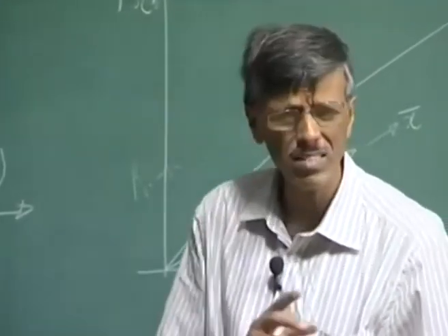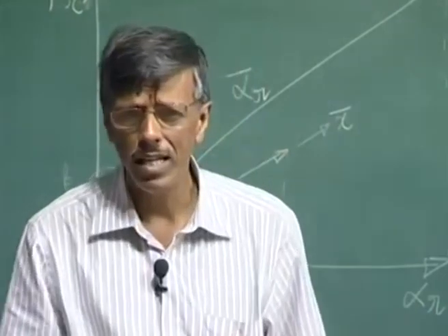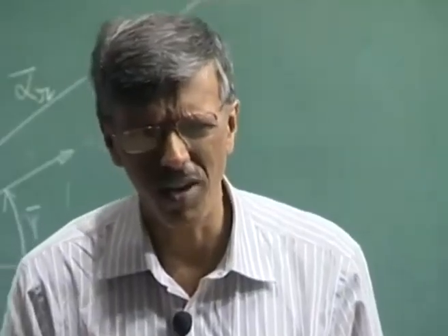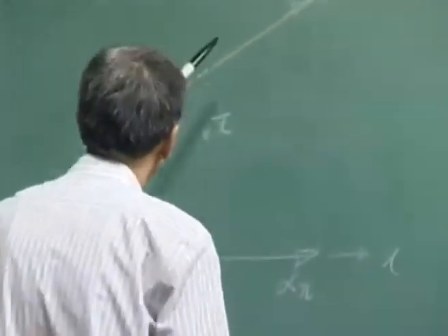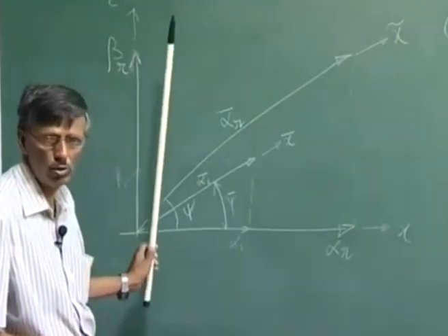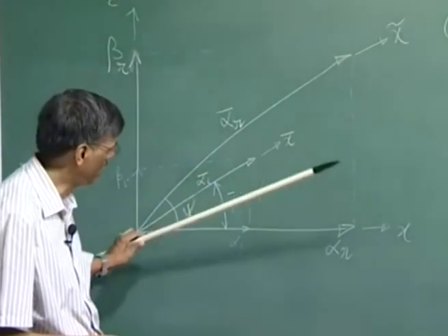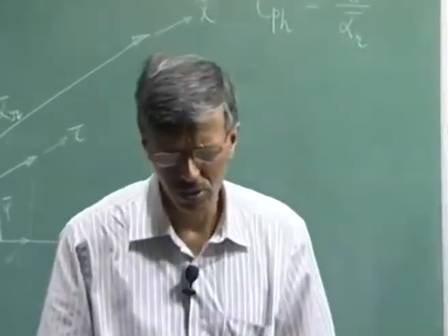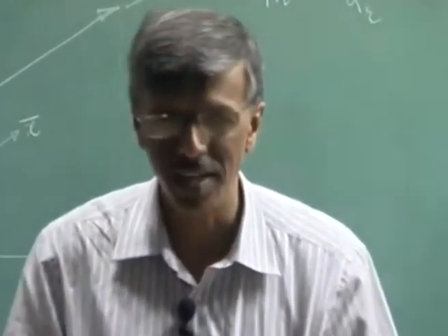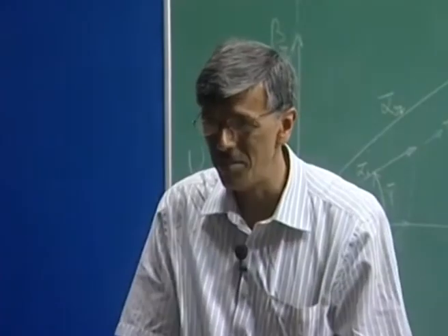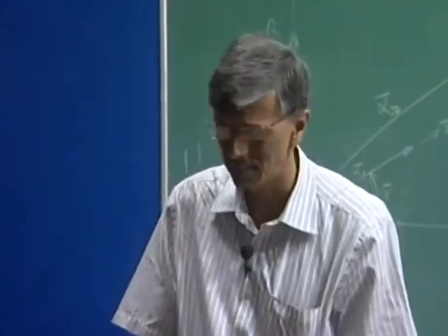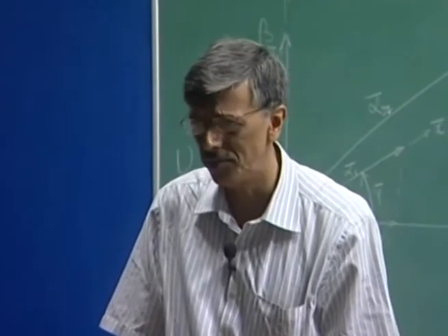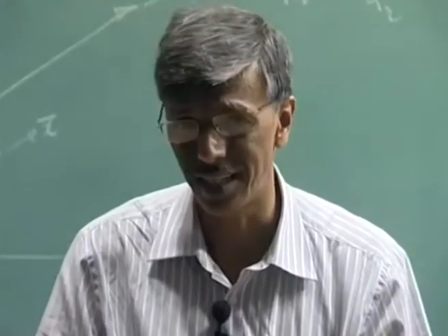And please do understand that these complications that we are getting are because we are talking about a 3-dimensional disturbance field. So, alpha and beta make all these things, but if I look at a 2D disturbance field, then everything goes in the x direction. So, all these complications are with respect to the 3-dimensional disturbance field. It is not imaginary or illusory to consider that, because if we are designing an aircraft wing, we do very often see that.